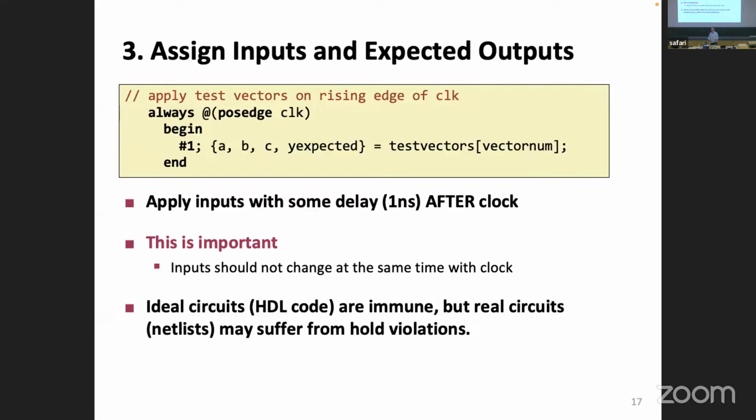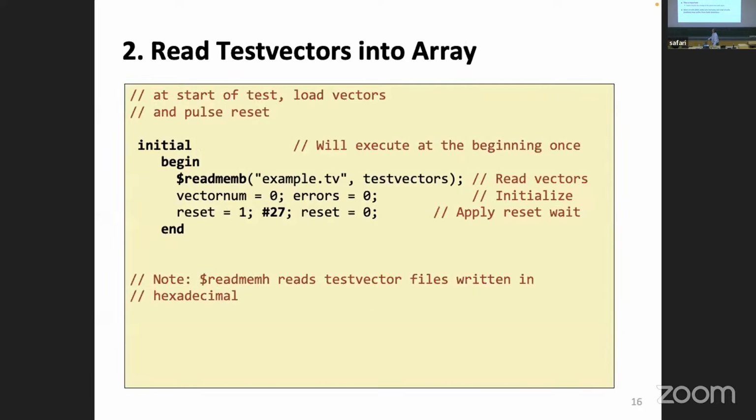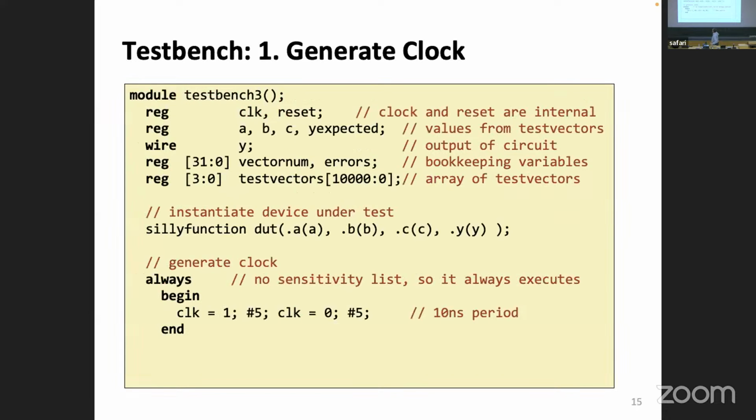Oh, that's simultaneous. Okay. Question. So the clock here, is it the same that our registers use? Well, we are talking about the signal that we have generated. Now, in this very particular example that I'm showing, the circuit doesn't need the clock. It's a combinational circuit. However, if it was a sequential circuit, and in the most general case it is, we would probably feed this clock directly to the circuit as well. So it would be the same clock.